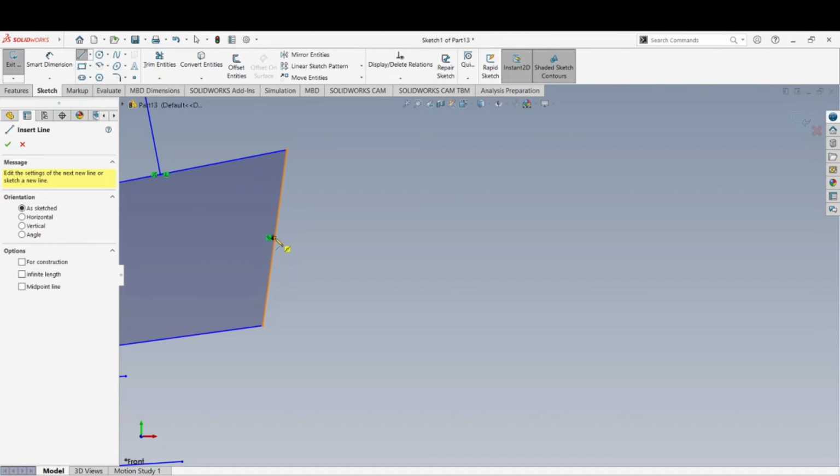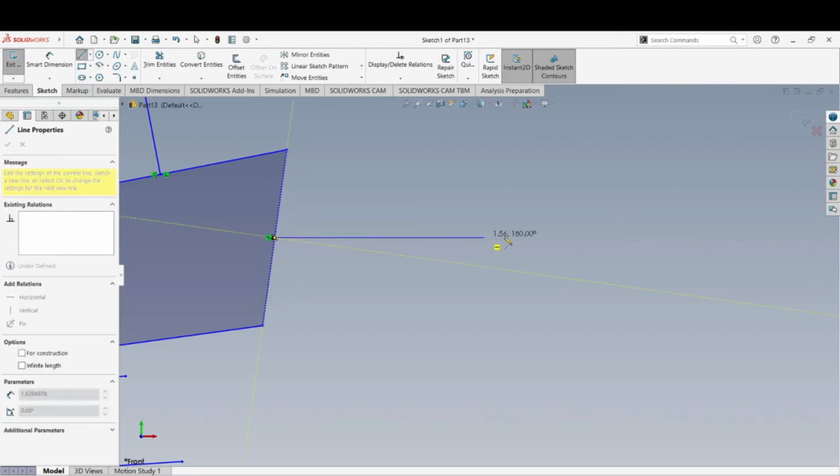That is going to snap the line, or that point of the line, to the midpoint of that line. And as you can see, this yellow is going to give us our perpendicularity. So it kind of tells us where perpendicular is, if that's what you choose. And if I click on that, then it'll lock the relationship perpendicular to that line. I don't want that for right now.